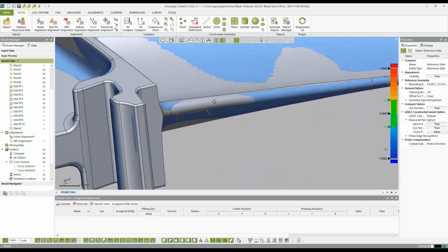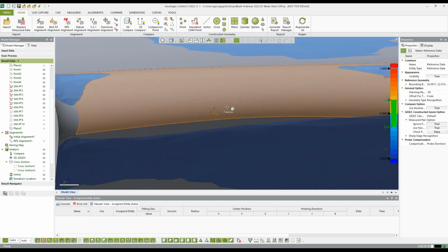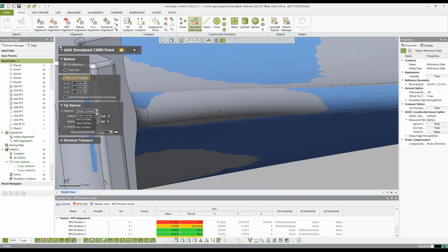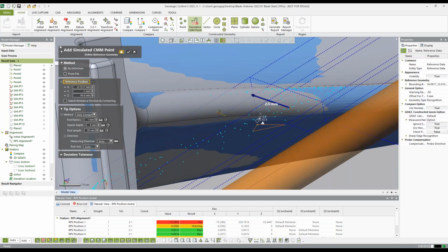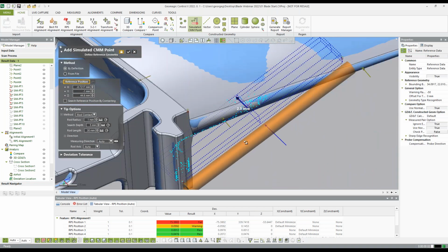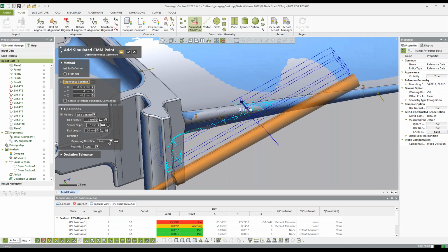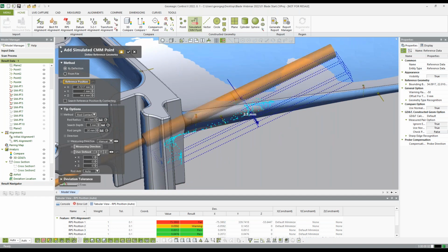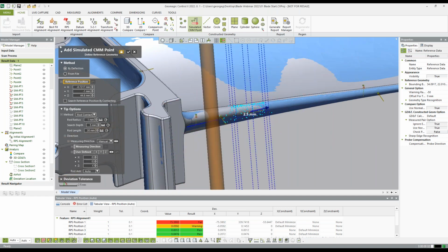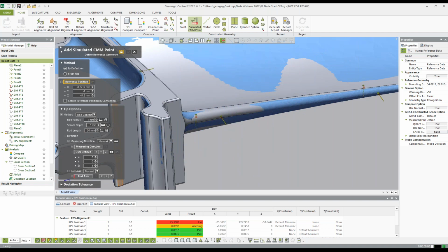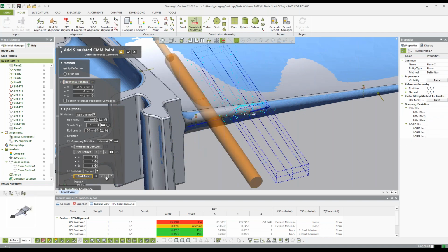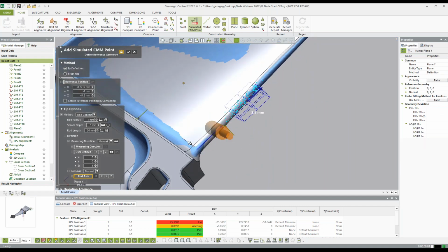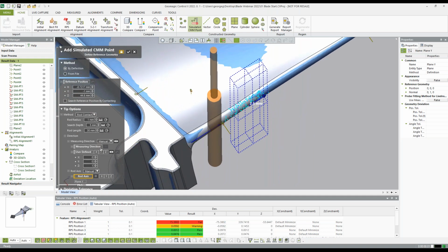Now they also happen to work well because you can create probe points, but you can also create not just probe contact, but rod contacts, right? So I can actually say I want to create a rod contact, and then I can change my orientation here. I can say this direction, that direction, and then I can apply these, like so. And I can apply my probe contact to the different directions.